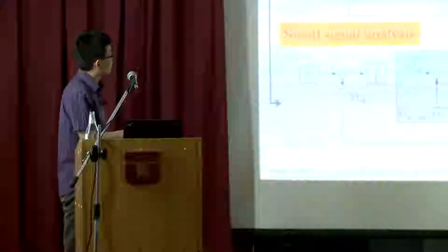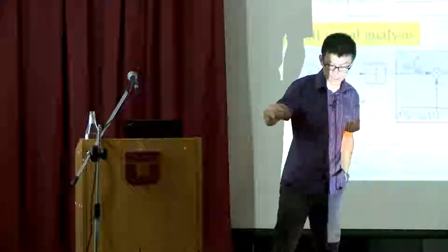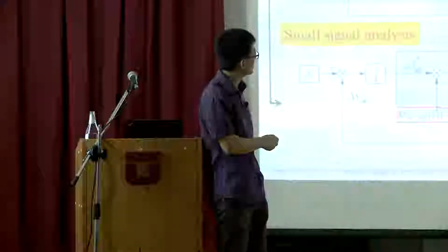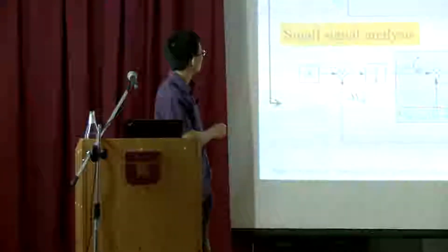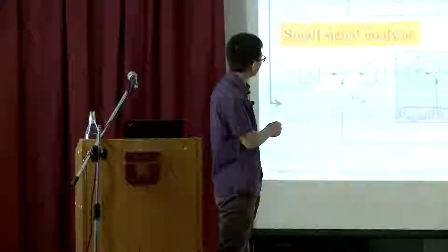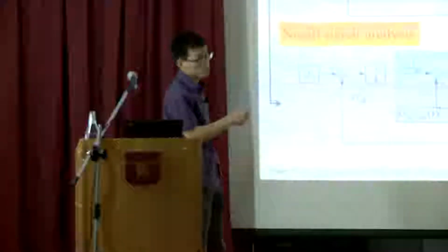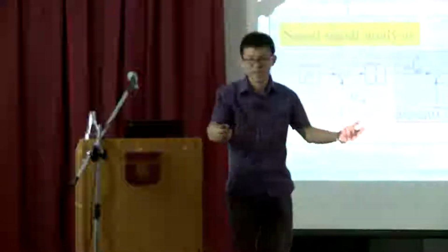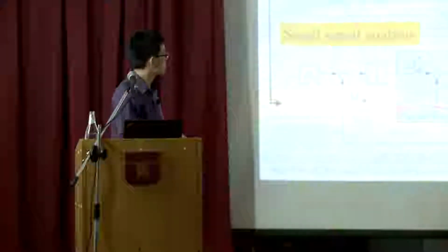And outside, of course, you have the IDC. You minus the load current, and integrating this current, you get voltage. So you get VDC output. So VDC feedback. So you get VO minus VDC. This is the droop, 1 over K. So this is essentially the current mode droop closed loop, single line diagram, and from there, of course, you can use the small signal analysis.